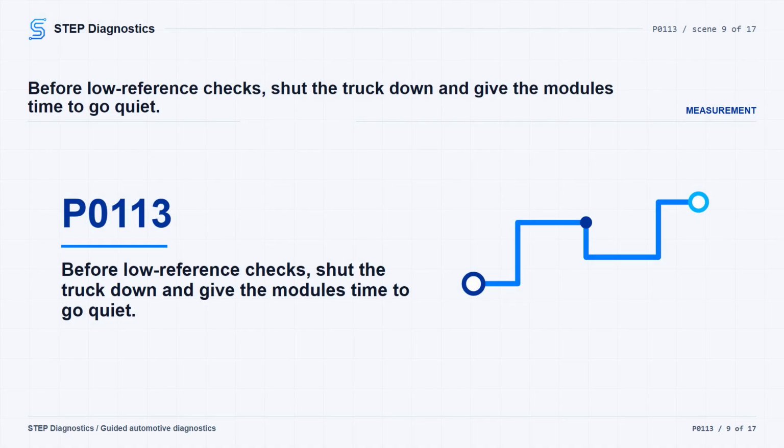For circuit testing, turn the ignition and vehicle systems off. It may take up to 2 minutes for all vehicle systems to power down before an accurate ground or low reference continuity test can be made. Disconnect the B75C multifunction intake air sensor. Test for less than 5 ohms between low reference circuit terminal 3 and ground.